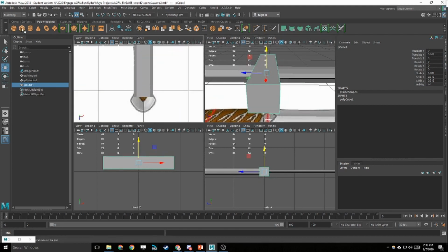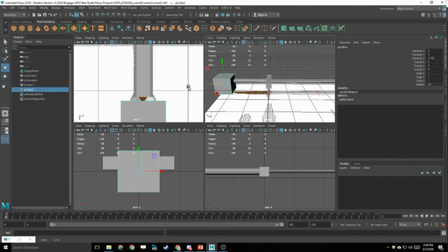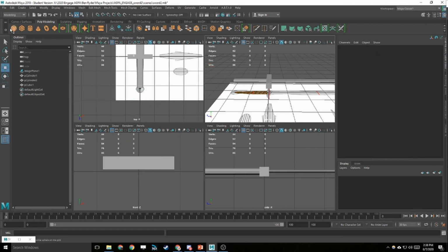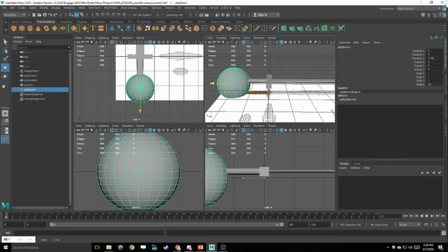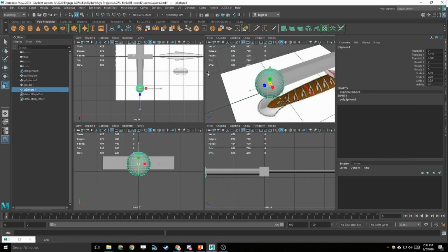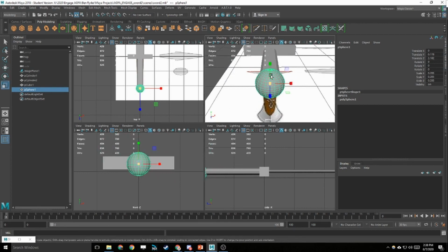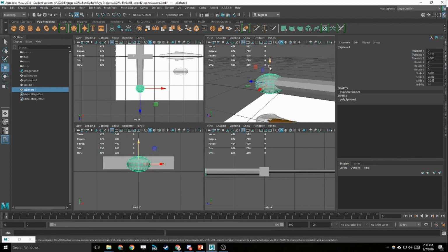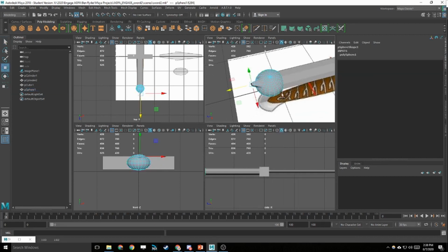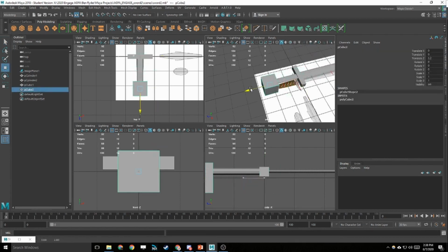And then down here, there's a number of things I could do. If I just wanted a basic shape here, I could just put that sort of shape here. I could use a sphere for this end one here, but I'm not going to. I am going to use a cube. In the next lesson, when we start looking at edge loops and bevels, we'll look at how we can get more of a rounder shape. Even though a sphere will give us the shape we want, it's got a lot of polys and it's very hard to start moving those and reshaping those. It's really hard to get the shape that we want without accidentally breaking it, and it will ruin the topology. So I'm going to instead just start with a cube.